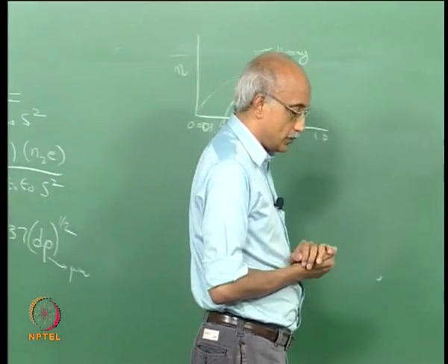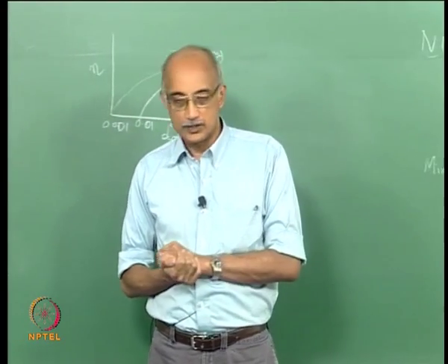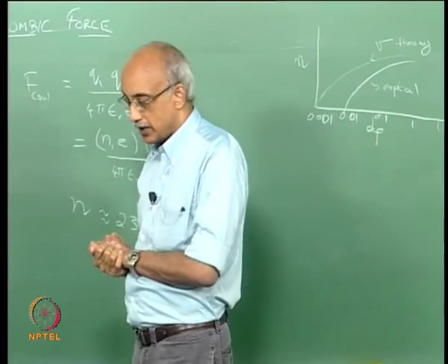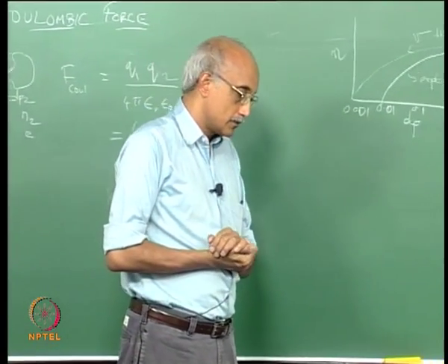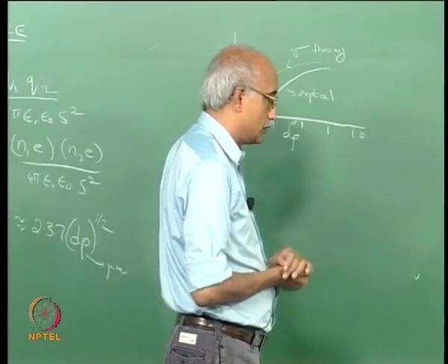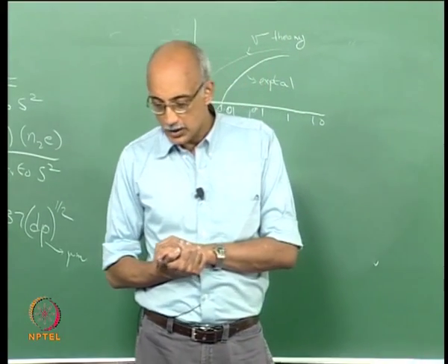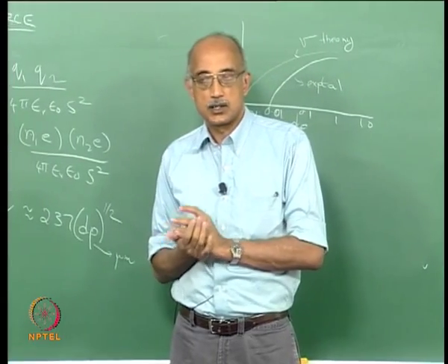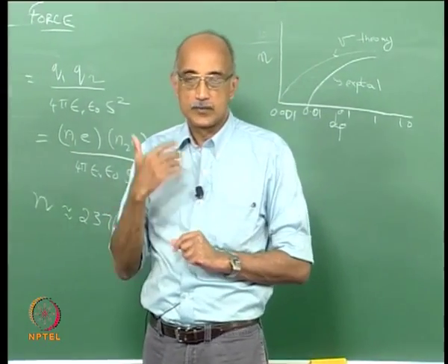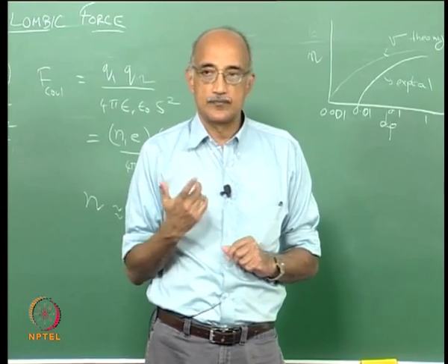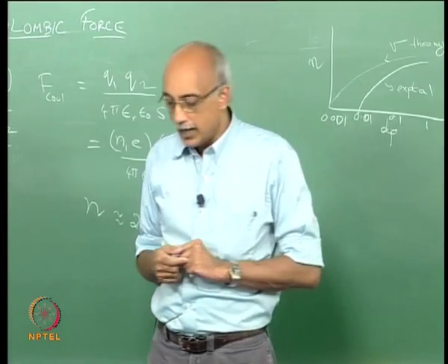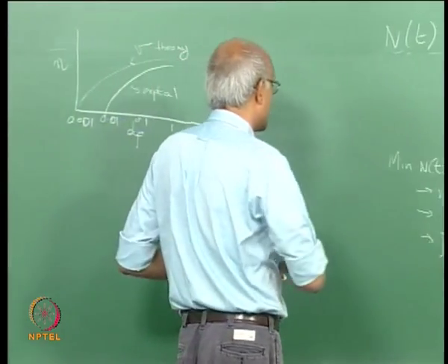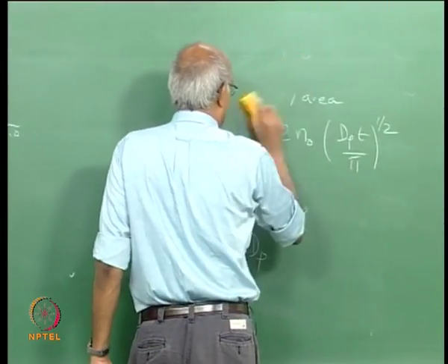Okay, so we have looked at essentially two transport mechanisms that are particularly important for fine particles. As you transition into larger sizes, as I was mentioning earlier, the macroscopic forces that are transferred to the particle by the surrounding fluid start to become increasingly important, and drag forces are among the more important forces that a particle would experience in a larger size range.